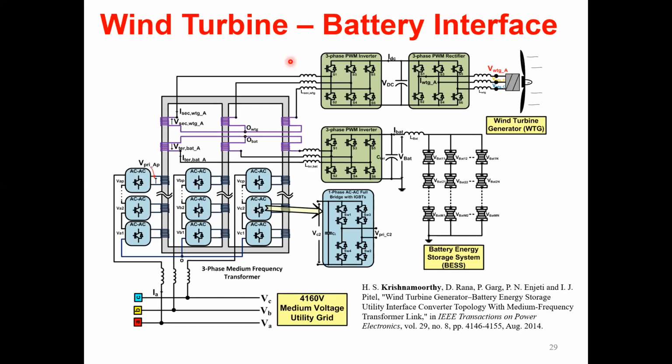So it's a very straightforward approach. I always prefer square wave switching whenever possible. Of course here we can do square wave switching, but for the PWM rectifiers, we had to have a combination of square wave and sine PWM. So it was a combination of both. You can read this paper to understand more about how that PWM modulation is taken care of. Since it is not directly relevant to the solid state transformer technology, I'm not going into too much detail in that.